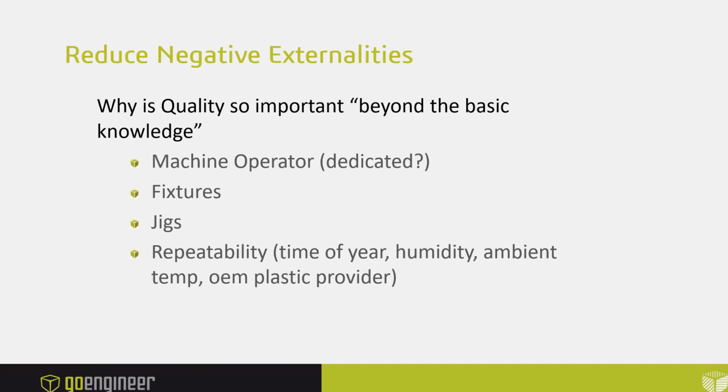Okay, moving on. What are some of the negative externalities? These are the things that happen down the road when we don't do a plastic simulation. We have a dedicated operator that doesn't just rotate to different machines, but also sits there at your machine and inspects every part that comes out. And why is this necessary? Because there are problems with your mold, because there are problems with the plastic flow. Because of the inconsistencies, you now have to pay for an operator to sit at your machine, in addition to the hourly rate, to inspect your parts and trim the gates.